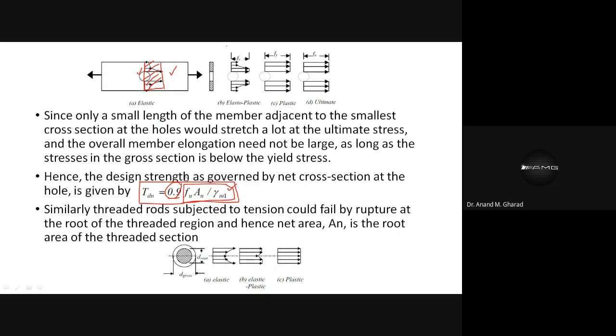So over here, since there is no deduction of any value as far as the bolt is concerned, isn't it? Bolt will be a solid part. It will be a homogeneous unit. And if that bolt is subjected to some pull, that capacity of the bolt will now be governed by its yielding capacity, or yield strength.